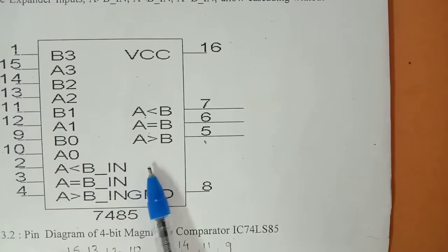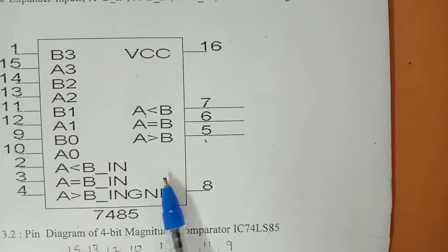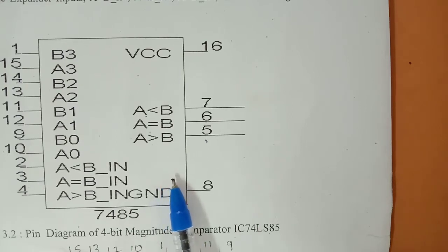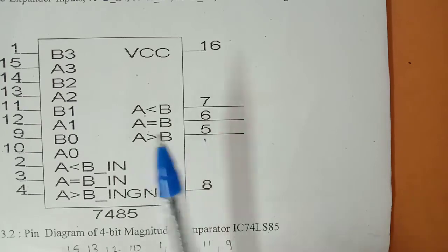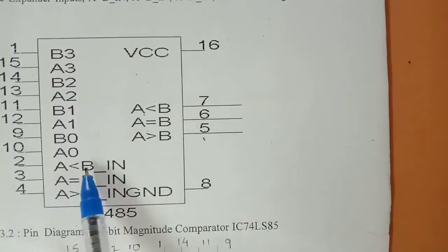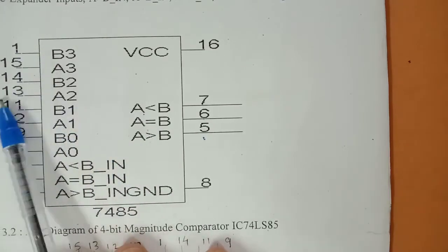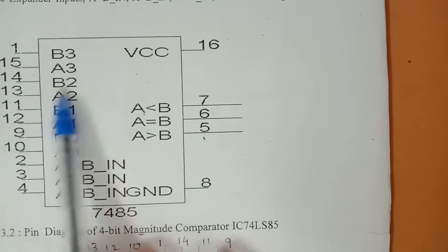Before performing any practical, I request all students to first download the data sheet of the respective ICs. It is mandatory before any hardware-based practical to download the data sheets. By referring to the data sheet, we have to draw this type of diagram. This is called a pin diagram. In the pin diagram, the labels define the purpose of the respective pins.